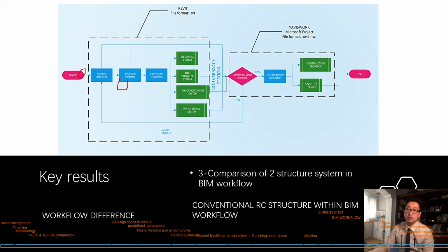After structure and architecture are done with their job, the other discipline engineers and designers can design and model their own subsystems based on the same Revit link. So there is not much chaos like duplicate and missing files. After all the models are done, because we use the same link, the origin is the same and the project location is all the same. So there will be fewer alignment problems. Next step, go to coordination and check.